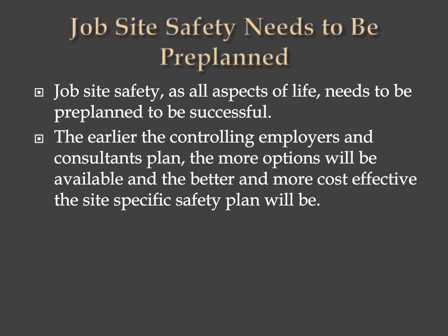If you're doing something by the seat of your pants, it never works out well, because construction continues at a very rapid pace, and you have very few options if you've done it wrong to begin with. Let me give you an example here. You plan on putting the building up, you plan on decking every other floor, so that you meet the 15-foot requirements for steel erectors. However, what happens is the decking doesn't arrive on time, even though you pre-planned it that way. So now what are you going to do?